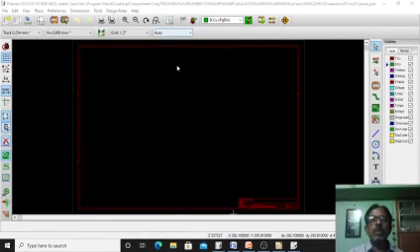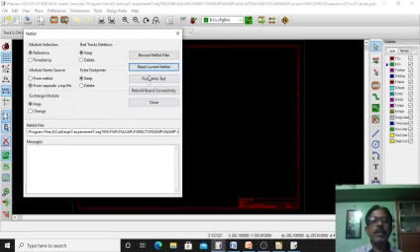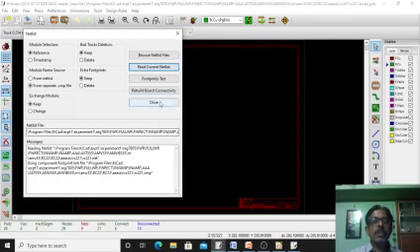Next, the first step is you go to net, read current netlist, then you say close.